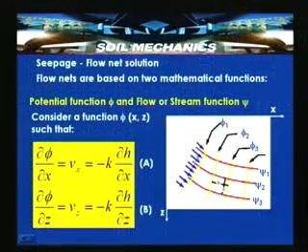This is negative because the head loss is occurring in the direction of flow. In this slide, a part of the partial flow net is shown. The red lines indicate streamlines, that is flow lines, represented by functions called psi 1, psi 2, psi 3, and these are the equipotential lines represented by functions called phi 1, phi 2, phi 3. So, the flow is occurring in this direction.